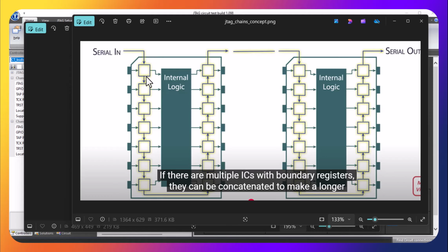And once you have signals captured in each cell, in boundary scan mode, you can then use that. Those will be broadcast to other cells connected to other pins on your board, and you can transfer. Once you run a test, you can then capture signals back into these cells and then scan out the captured data, and in this way you can do a structural test of your board.